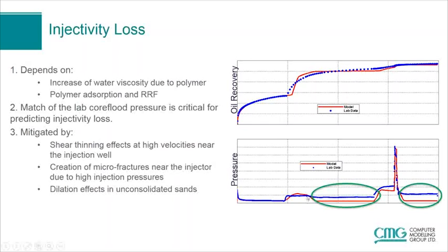It's matched well up until the end of the first slug of polymer injection. And then the simulator drops below the measured value. So there's some residual value here that's not captured properly. And same thing, if not worse, on the second slug, there's this substantial difference here. So that would mean that the injectivity after polymer injection stops would be too optimistic as predicted by this particular model.